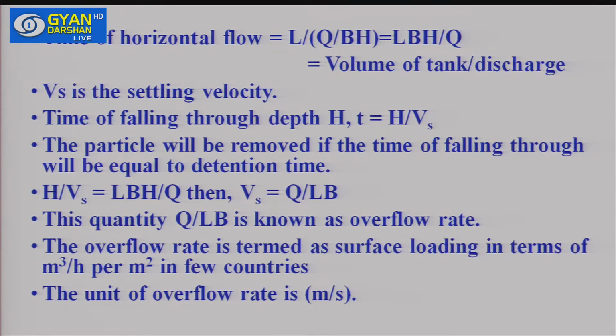After flocculation, as I told you, this water is sent for filtration. Here the sand filters are used. Through the sand bed, water trickles, and any impurity which is there in the water is trapped in the sand filters. Then we get safe water. Then there may be some bacteria or microorganisms. They are removed by the disinfection process, in which we generally use chlorine, and finally we get the safe water. So this is the process by which we treat water to make it safe for drinking purposes.